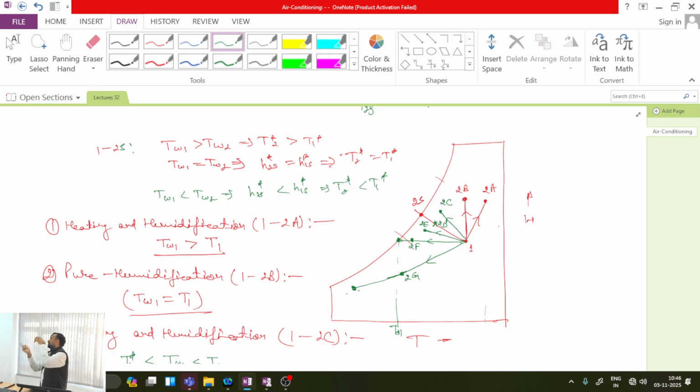These water droplets come in contact with air and it leads to the process of cooling and humidification. That's why from the top of the cooling tower you see white fume coming out. It means that the air is almost in the saturated state, so it contains a significant amount of water vapor. So when that water is evaporating, in that process the air and the remaining portion of the water are cooled. At the bottom of the cooling tower that cold water is collected, and it is then again recirculated to the condenser.